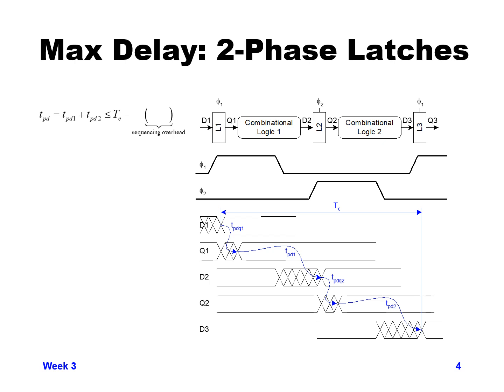In this case, let's say we do have the data coming in, so D1 is coming in around the time that the latch opens for phase 1. We get a certain propagation delay through that latch, and that causes the output to come out at Q1.